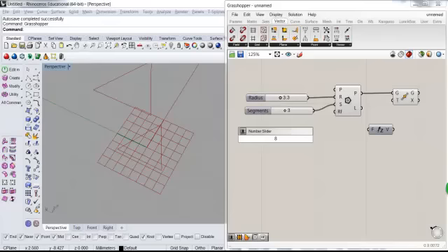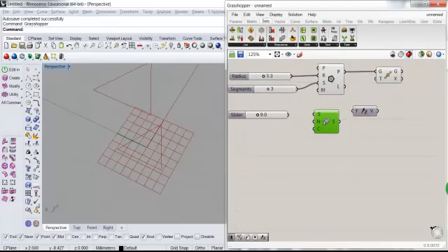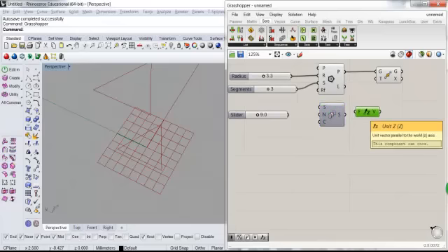I just say 9 inches at this moment, because it's another parameter. I can change it on demand, but at this moment, I just make it 9 inches tall. And we need a sequence. We need to move the basic geometry to different levels. So we just create the series of heights for them.